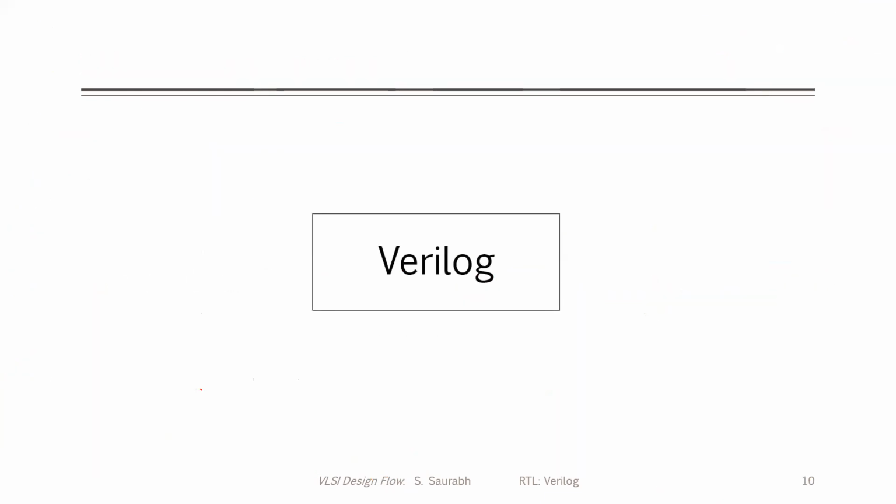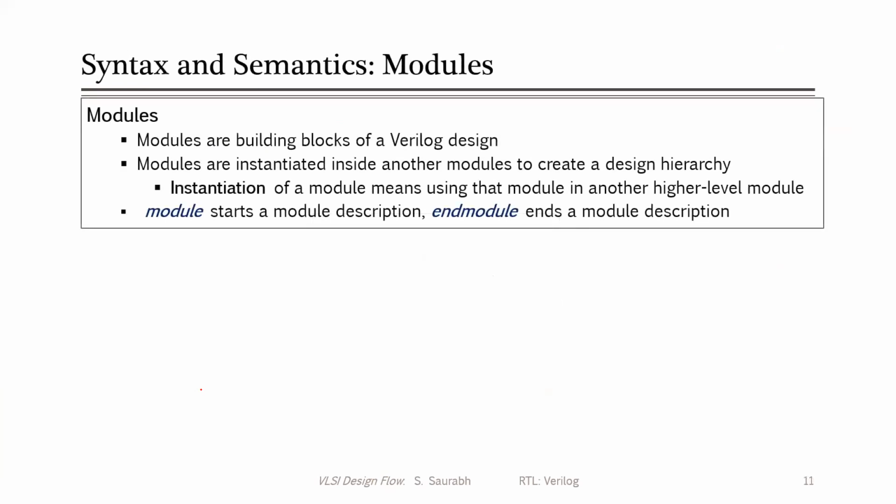So let's move now to Verilog, and I'll describe some basic syntax and semantics of it, and then we'll go into simulation and other aspects. In Verilog, modules are the basic building block of a design. Modules are instantiated inside another module to create a design hierarchy. As we saw in yesterday's class, a module starts with the keyword module and ends with endmodule.